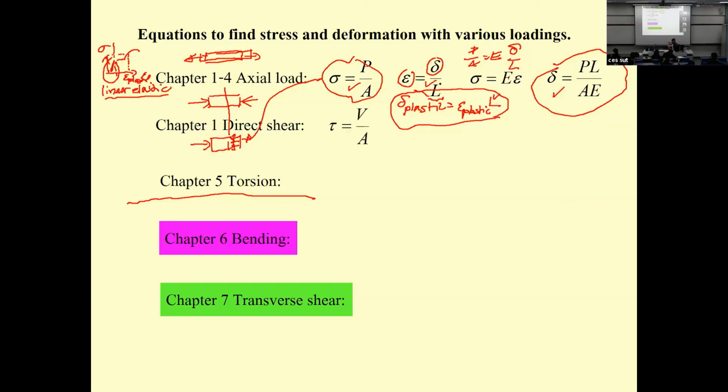And then we come to the shear. The shear can be separated into single shear and double shear. For the single shear, it's very easy. Just do something like this. We pull together. There is one cut, right? The force that I pull you is going to be the shear force here. And somehow we have this kind of connection. Two of your hands are put in my hand, and what we have is double shear because we're going to cut this portion and also this portion. They are double cut. So this shear is going to be half of my force.